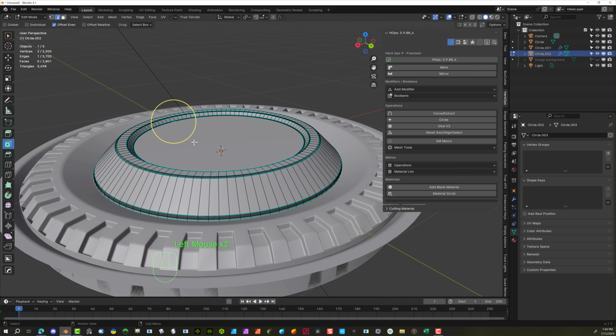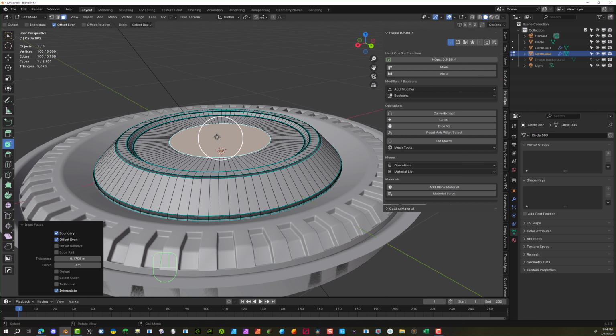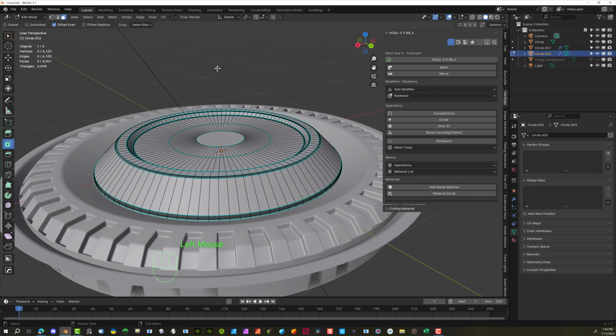Okay, let's go and select this face here. Actually, select the face tool. And again, we're going to inset this. So hit the inset tool, pull this in. About there. One more time. Cool. Now we can also extrude this in. So let's make sure we select the face here, and extrude with the E key or use the button. And we're going to bring this up.